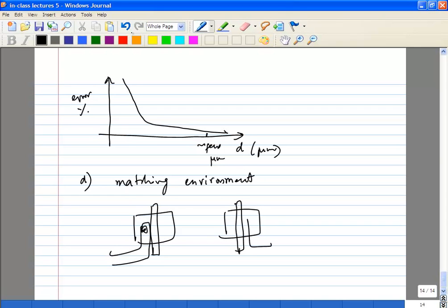Okay, and you still want matching. So then you still add the metal line, but no contacts, so that at least there will be overlap parasitic capacitance from the metal line onto this. So you have to worry about matching capacitances in an RF sense. Or you could, for example, have a supply line, let's say VDD, running all the way here. So what you'll probably want to do is extend it. Very small things like this can make a big difference.